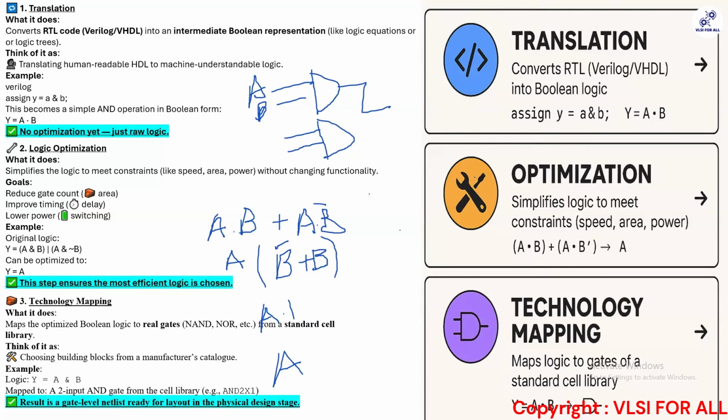What is the voltage? The same design may be operated at, let's say, 0.6 volt, and some same design is operated at 0.67 volt, because you don't know exactly. When you look at a bigger picture, there can be a lot of IR drops in your design.